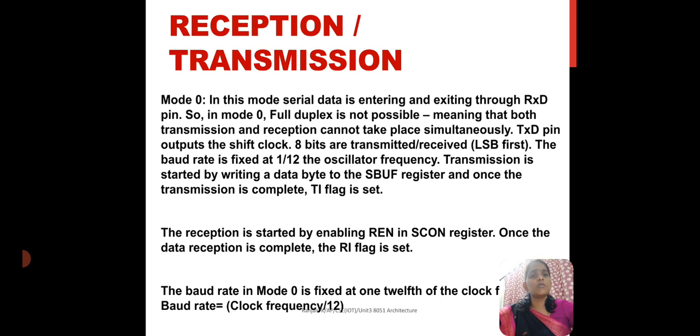Next is reception and transmission. In mode 0, the serial data enters and exits through the RXD pin. In mode 0, full duplex is not possible, meaning that transmission and reception cannot take place simultaneously. Here the reception is started by enabling REN in the SCON register.